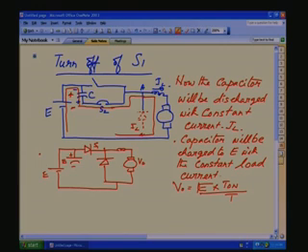But in all practical circuits, the thyristor will take some finite turn-off time, which you can find from the data sheet. So any thyristor will have a minimum T off time. During the full T off period, we have to apply the reverse voltage across the thyristor.